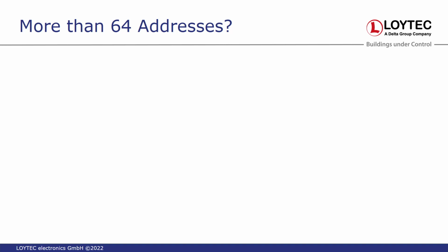I understand. Or is overloaded. And I'm mainly in the field, and I can tell you that a lot of the time the bus will be overloaded by the contractor. They will try to put more fittings onto the DALI line than is recommended. So normally what some other manufacturers do is we pull in the short addresses, sorry. And once we get up to 63 or 64, it will stop and inform you that you have too many devices on the network.